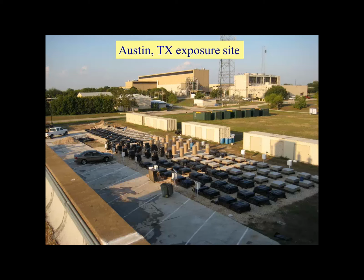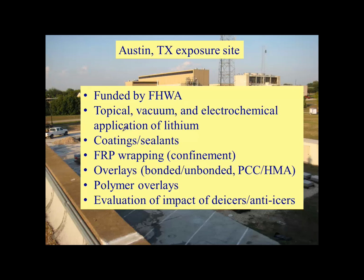What we've done is we've triggered ASR in all of this concrete using 2 different reactive aggregates, and at a level of expansion of about 0.1%, various mitigation techniques were then applied to these different elements. They included topical, vacuum, and electrochemical treatment of lithium, the use of coatings and sealants, particularly silanes, the use of FRP wraps on circular columns, the use of overlays, bonded and unbonded, and including Portland cement and hot mix asphalt, and also polymer overlays as well.